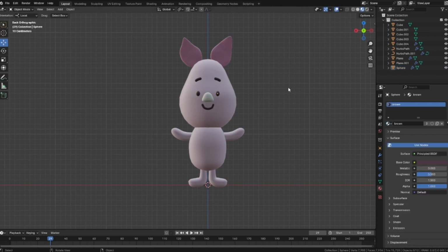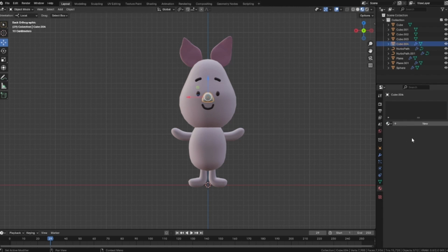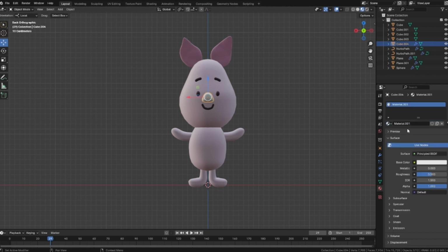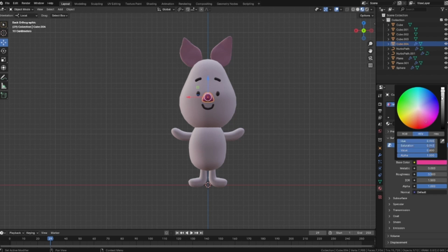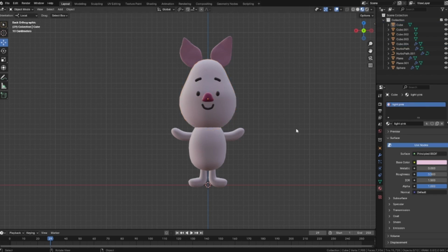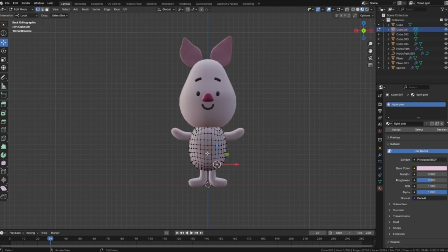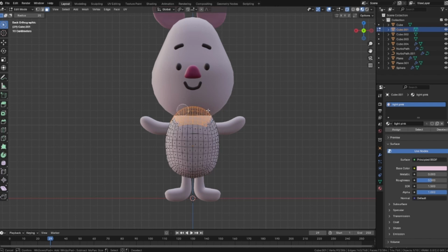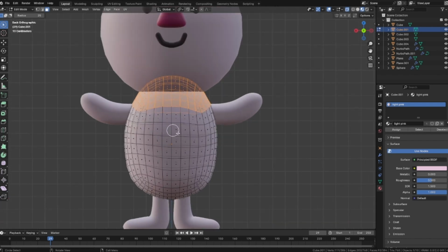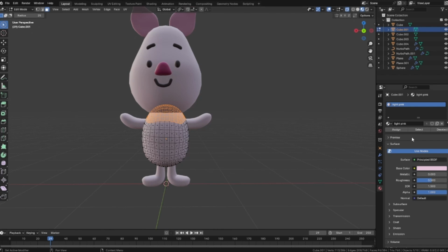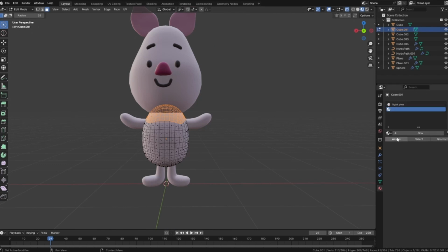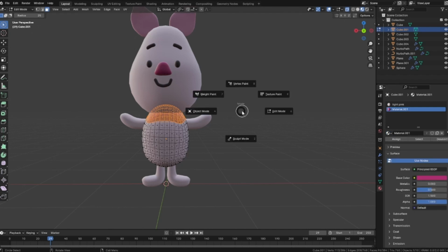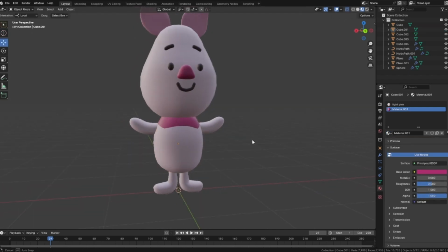And for the mouth also we choose brown, and for the eyebrow also we choose brown. And now the nose. Nose is a more saturated pink. Something like this. Now select the body and hold and select circle. Give it the face selection and select these parts. To remove, press Control; to select, press Shift. Then go to assign and select this material and click assign.